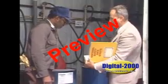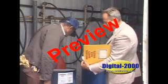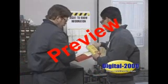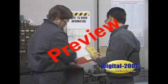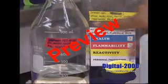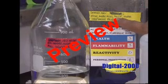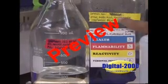Each chemical produced by a chemical manufacturer must have a Material Safety Data Sheet, MSDS. The MSDS is a summary of the important health, safety, and toxicological information on the chemical or the mixture ingredients. Other stipulations of the Hazard Communication Standard require that all containers of hazardous substances in the workplace be labeled with appropriate warning and identification labels.